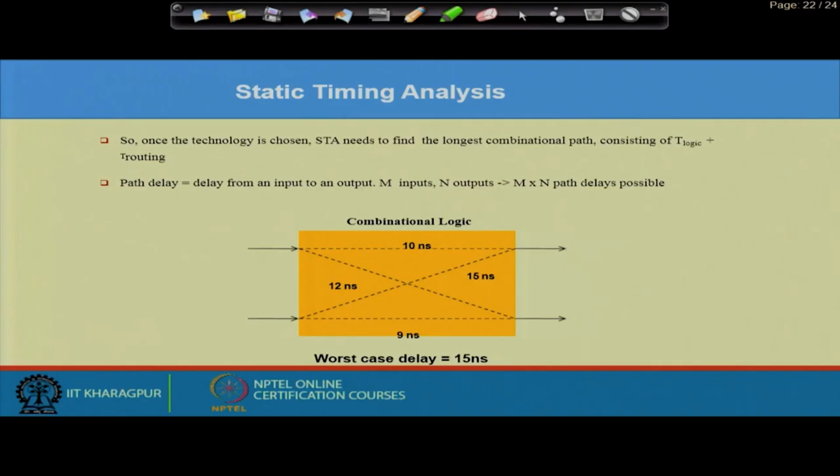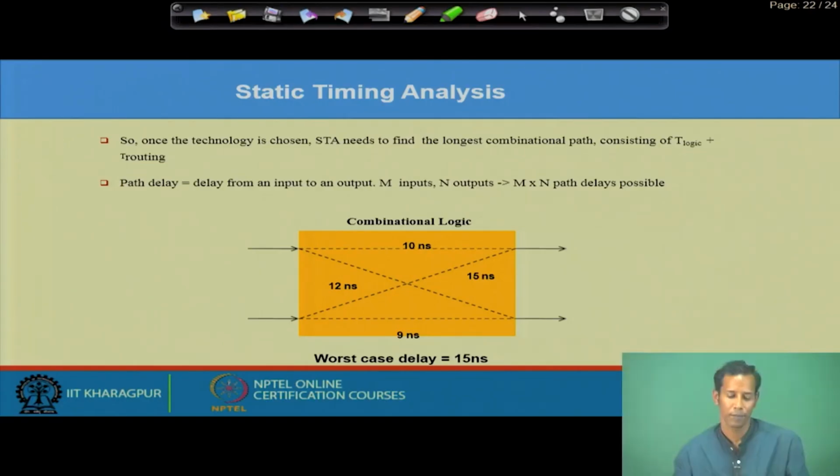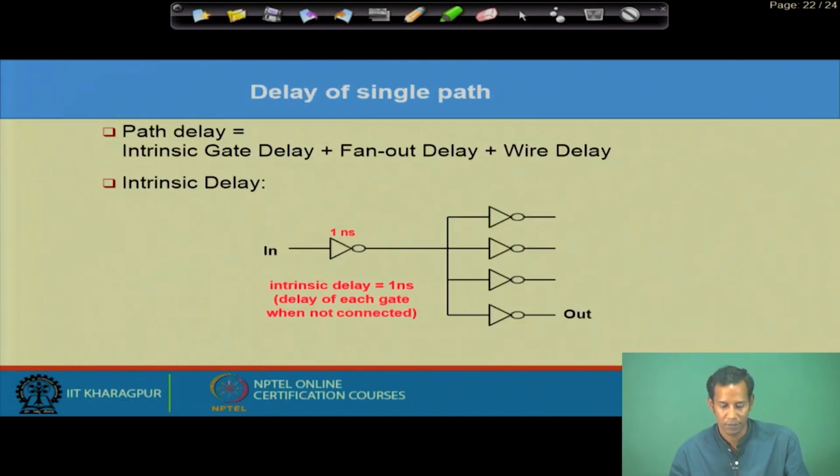So, we are basically considering the timing analysis basics, whether that is static timing analysis or dynamic timing analysis. They are very important whenever we are considering any digital circuit design or digital integrated circuit design. In static timing analysis, we have already seen that there may be many paths from input to output. The path with the maximum delay sets the cycle time requirement of your circuit design.